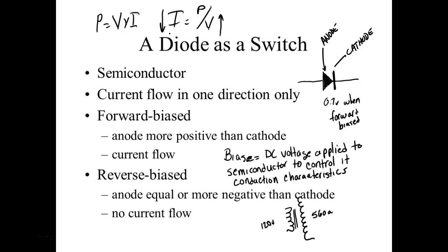Every wire has a resistance. This is the problem you have on your car batteries. Your car batteries require 50, 60 amps to turn that thing over, and that's probably in the summertime, almost 100 amps to get your car turned over in the wintertime. If your conductor had 1 ohm of resistance in it, your car would never start, because if you try to pull 50 amps through 1 ohm, it would drop 50 volts. So that's why your battery connection down to that starter are what? They're big old wires, right? And they're very short.